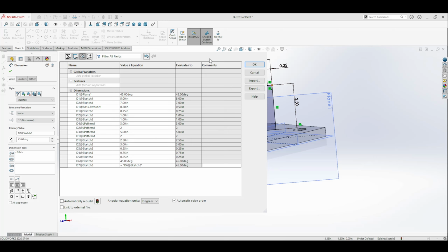That's what designers use. In the industry, they'll use this a lot. Regularly, you'll have configurators in things, in SolidWorks, in Inventor, and all the tools. You'll have configurators that use equation-based calculations and equation-based dimensions to size your part and your features and your model.